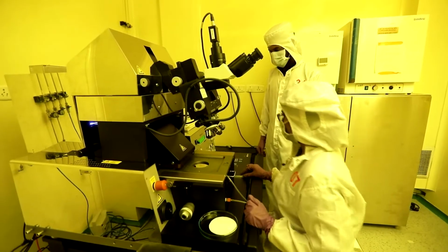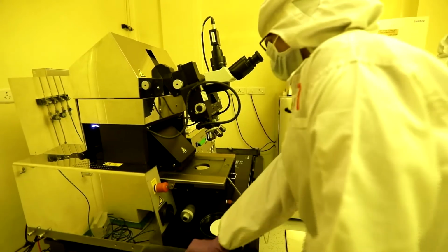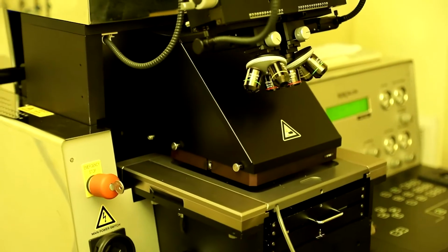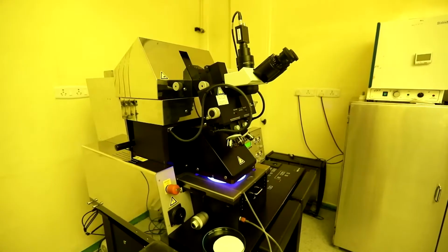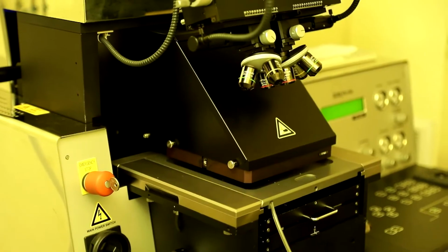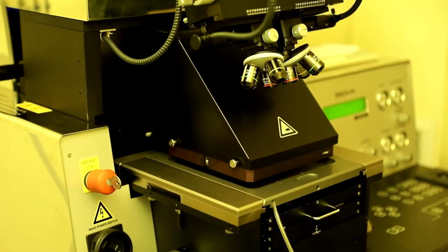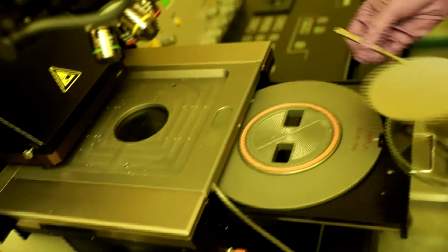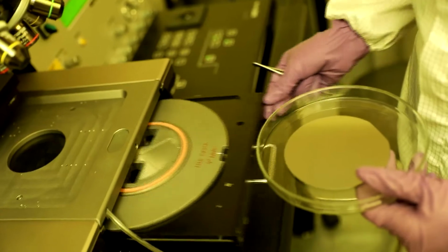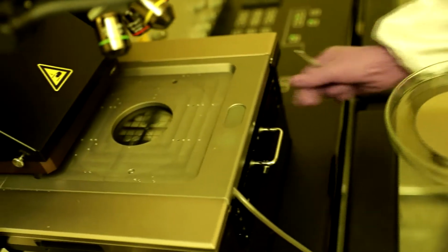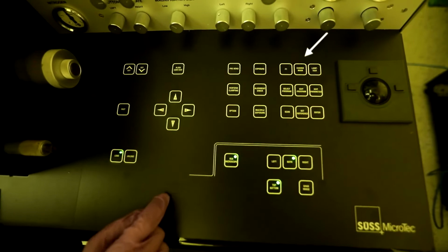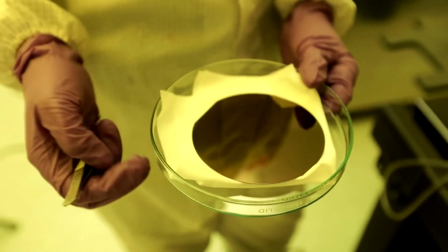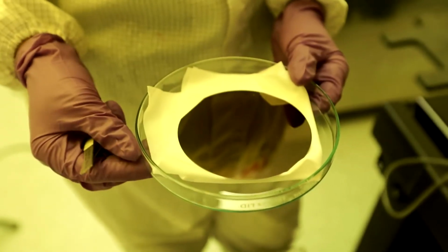When the alignment is done, press Exposure. Move away, as you should not look directly at the ultraviolet light or its reflection. The exposure process will be over in just some seconds, that is 18 seconds. After the exposure is over, pull out the substrate holder, unload the substrate, and put the holder back in place. Use Change Mask option for unloading or changing the mask. We will see the transferred patterns on our wafer after the development.